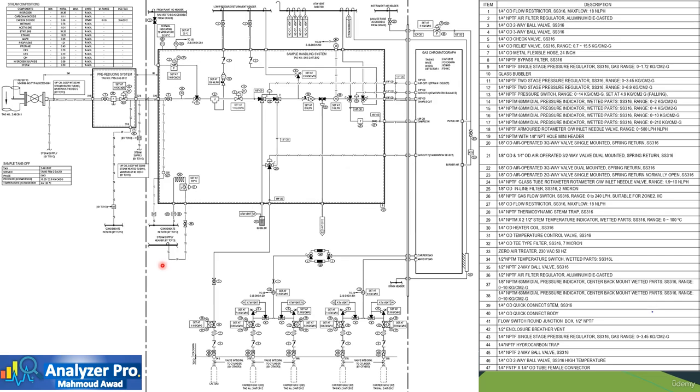In this example we have added the pre-pressure reducing station before the sample conditioning panel to reduce the process pressure from 16 bars to 3 bars. Also, the lines are all steam traced.